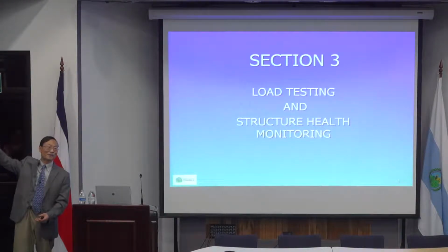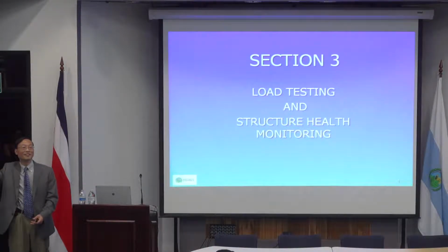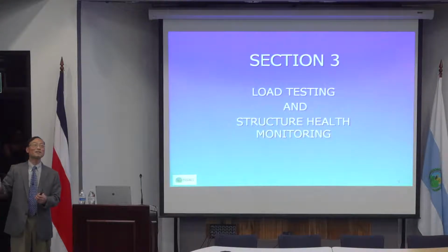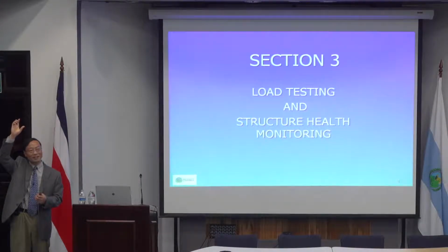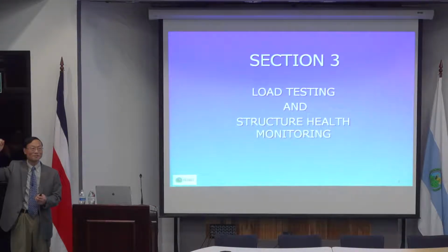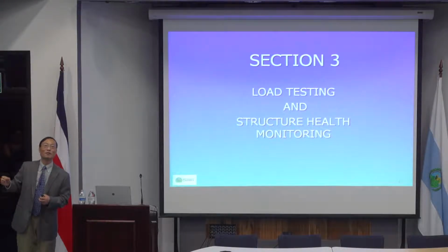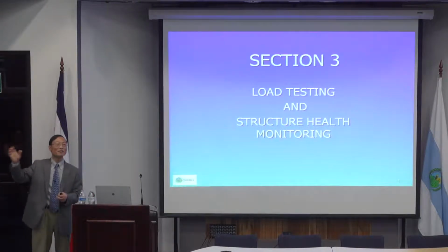You just measure the stresses of all these girders, and then you will be able to know how the live load will be distributed. Typically, you measure the stresses and deflections to have more data. The reason we collect more data is that later you need to play around. And that's one thing, how they are distributed.